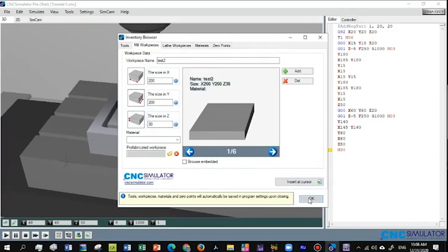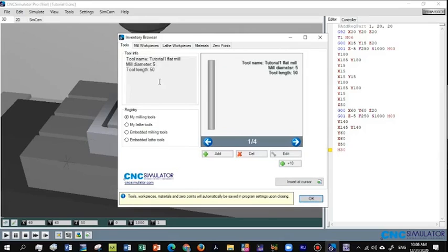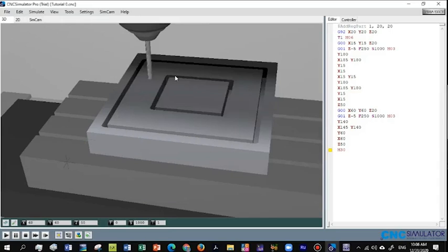So it depends on what the requirement in the question is. You need to define your workpiece here. And the second is the tool that you are going to use. If you are going to use the milling tool, you need to select the milling tool. If you are going to use a lathe tool or turning tools, you need to define these tools. In our case here, we are using milling tools, and we need to define also the diameter.